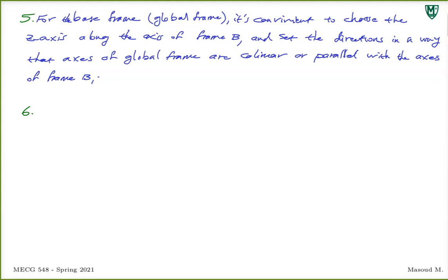You have to always make this assumption when you have a robot arm or serial link manipulator: you have to make some assumption about the final joint. Is it a revolute joint or a prismatic joint? Because if you don't know that, you can't set up your coordinate frame for that joint. Remember, there is a link, and you always attach the frame for that link to the joint after. So if you're in your last link, there should be a joint after.